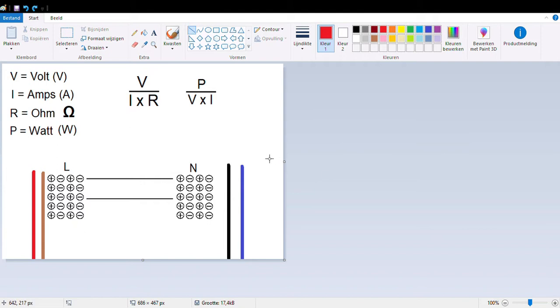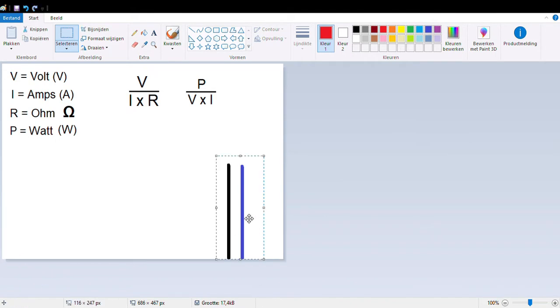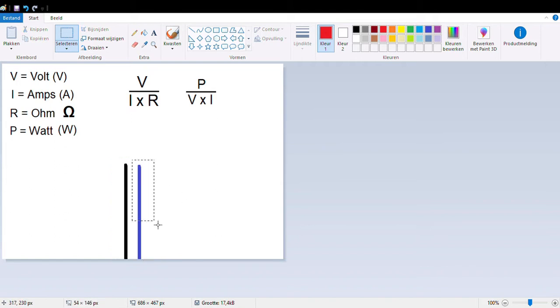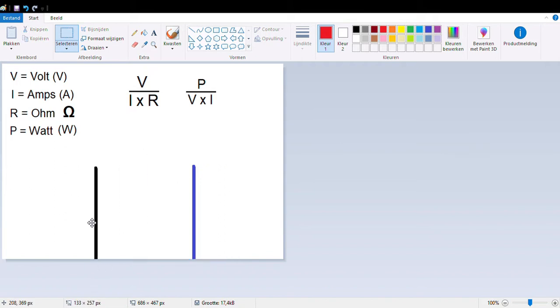And then the ceiling, where usually there's a light hanging there, it has a light switch. Well, then everything has changed, and I'm talking about the Netherlands, about Europe. There's probably a black and a blue wire there, which indicates the blue wire remains the same. It's still the neutral line, and the black wire would be replacing the brown wire, which would be the live wire, but then it's behind a switch, the light switch. So this wire could be turned on or off. You never know unless you measured it or unless you see a light burning or something. So that's another piece of information for you. Okay, let's continue then.